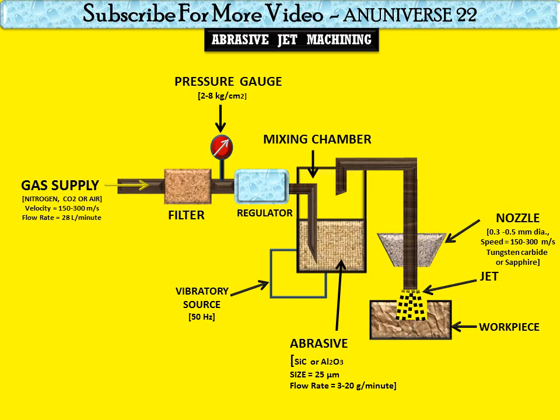Typically the abrasive particles from the nozzle follow a parallel path for a short distance, and then the abrasive jet flares outward like a narrow cone when sharp edged abrasive particles of aluminum oxide or silicon carbide hit a brittle and fragile material.